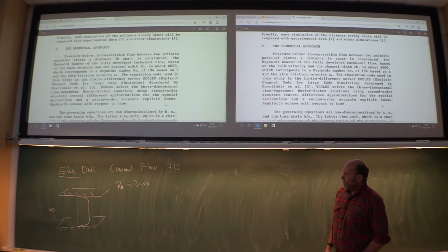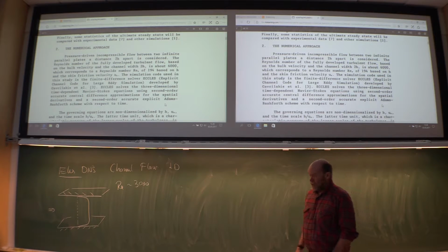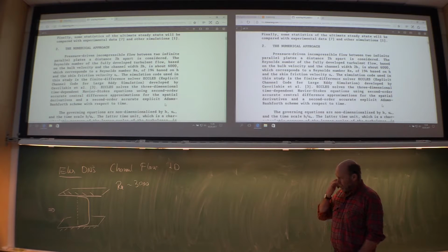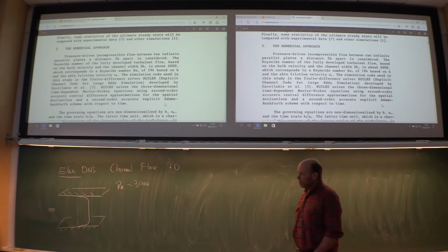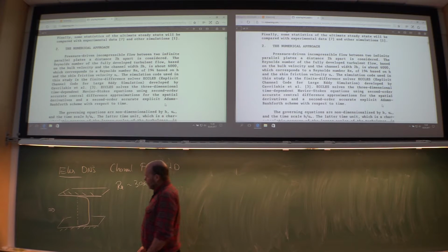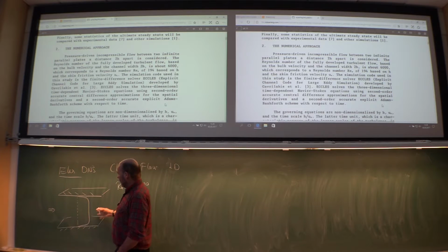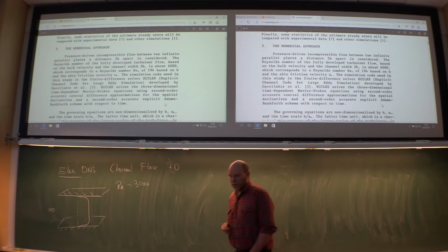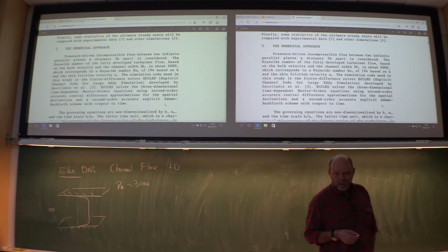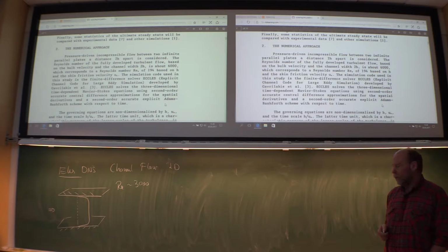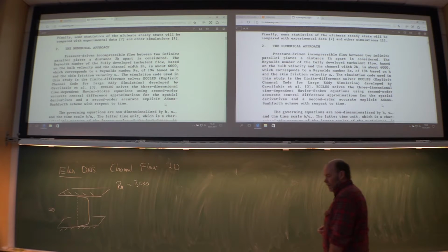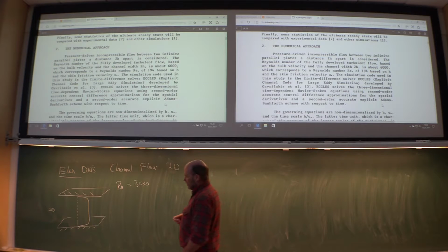And now the problem is as follows: the boundary conditions. How can we create a boundary condition here? I want a fully developed turbulent flow. So that means you can't send in a flat velocity profile and let the flow develop into a fully turbulent flow. Well, you could, but you will take forever to achieve a correct solution.